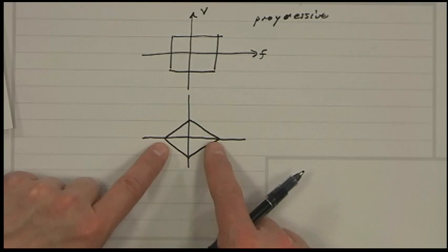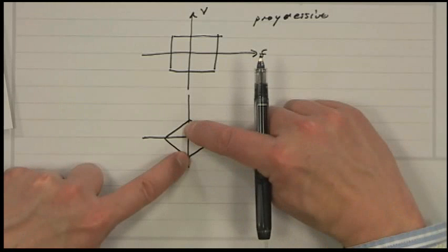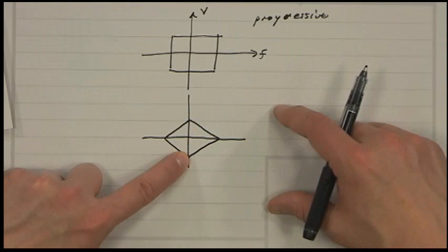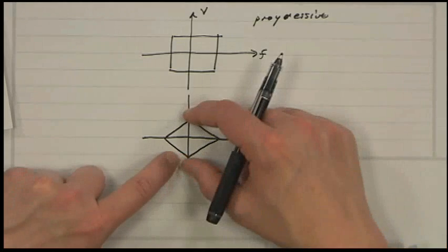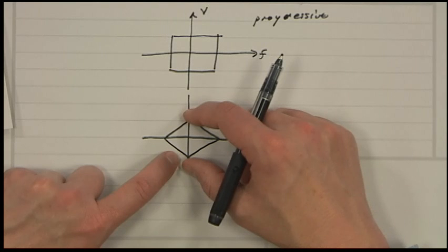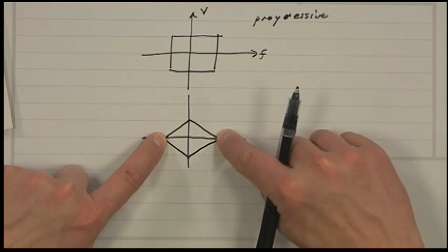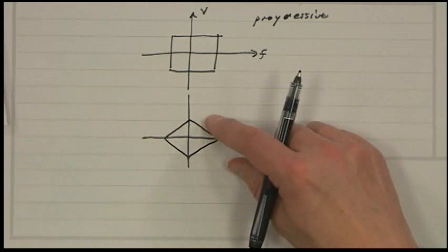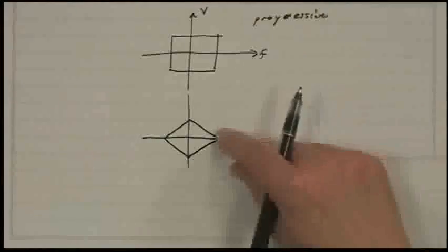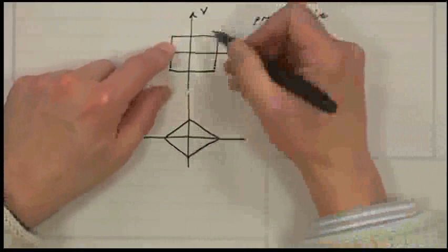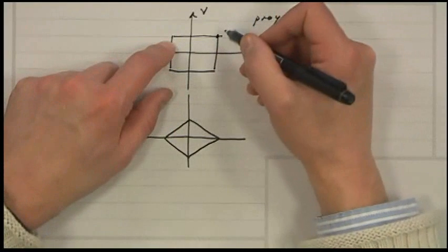So what this says is that if you have a stationary scene, then you get the full resolution here of the 1080 lines. In other words, if you have a fixed thing that's not varying, then you get the higher spatial resolution. But if you have something varying rapidly that's got low spatial frequencies in it, then you get the higher temporal frequency. So this is for half the number of samples. For half the number of samples, you get almost the same coverage, because the theory is supposed to be that this stuff out here doesn't happen that often.